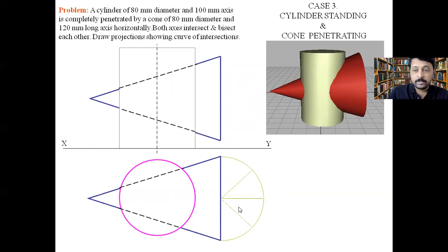Okay, so yesterday I told you that the more parts you make, the more accurate the curve of intersection you get. So let us say we have 1, 2, 3, 4 parts. Basically, if it had been a full circle, it would have been 8 parts. So we have taken 4 parts of a semicircle.